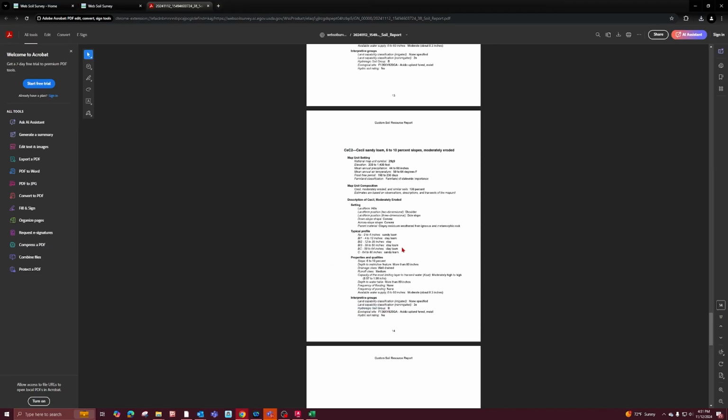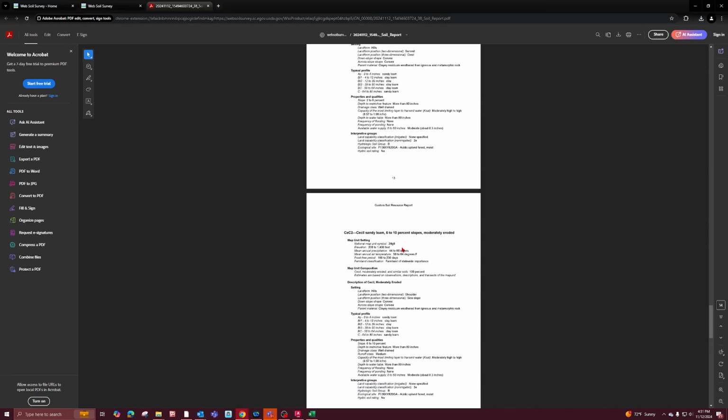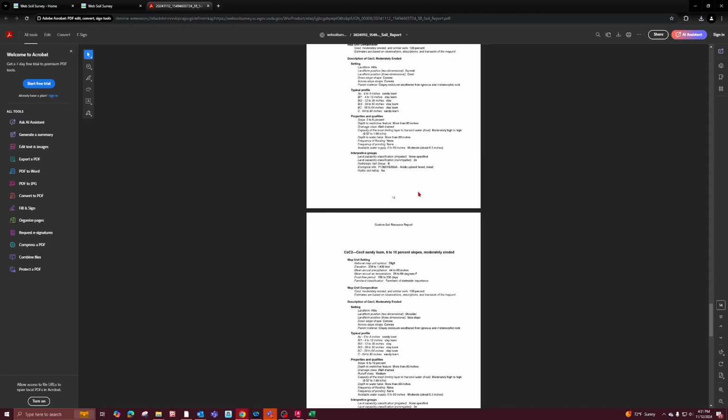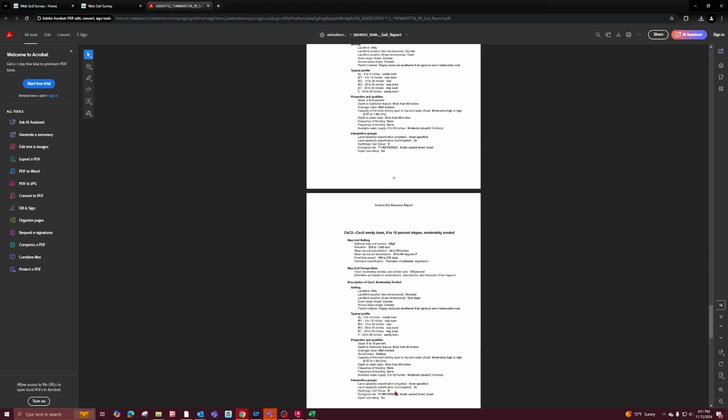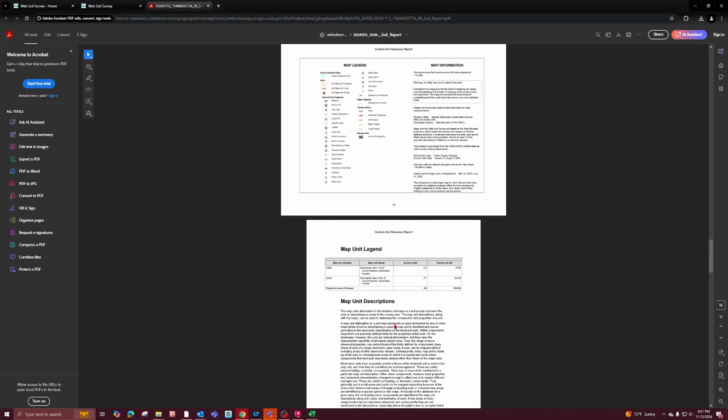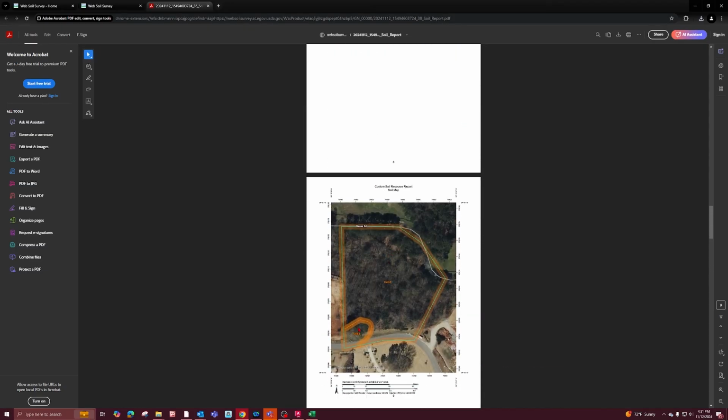So in both cases, it's good that both soils are B, so you don't have to account for different curve numbers for different soil types. Sometimes it will come up, like if this was B and CeC2 was maybe C. Since CeB2 takes up such a little portion of the site, I would just use whatever soil group type CeC2 is to avoid trying to make it super complicated.